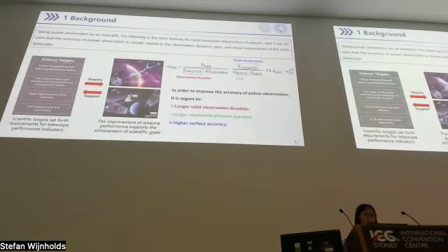So we innovatively propose an active regulation strategy for wind fields at antenna stations, and further invent an optimal strategy for wind field regulation aimed at mitigating wind load effects by optimizing the structural parameters of the wind regulator. The key to the research is to design the wind regulator scheme according to the special topography and geomorphological environment of the radio telescope site.